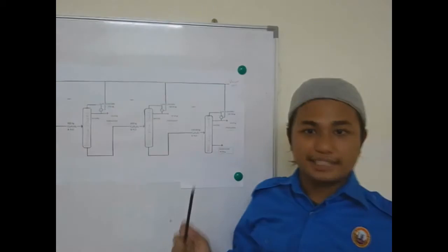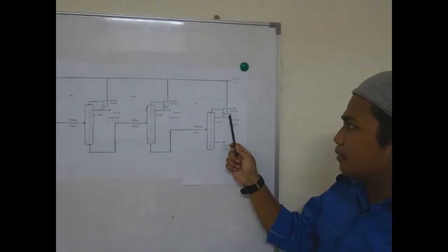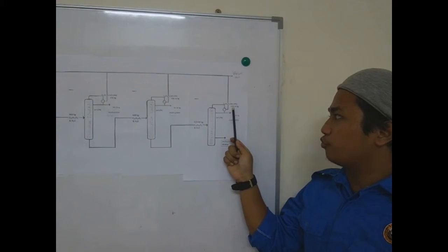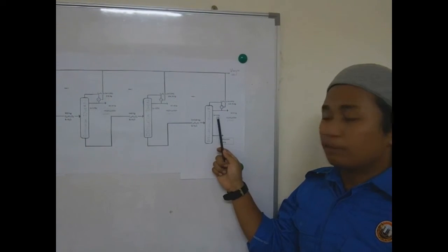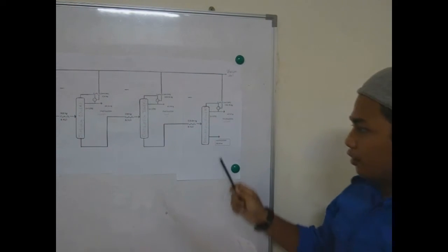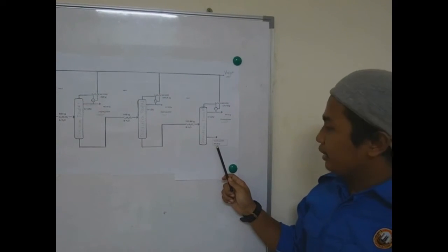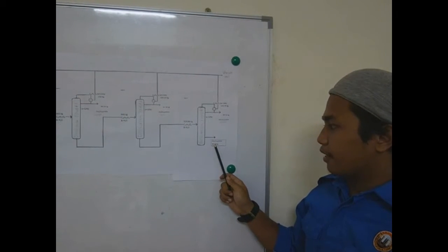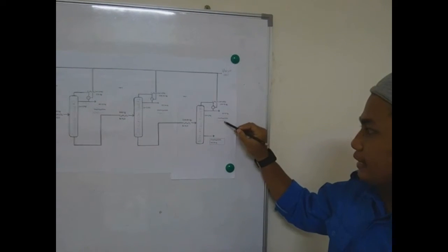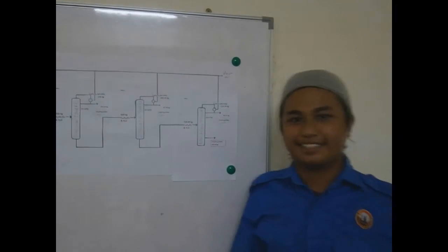Okay, the next material balance occurs in distillation tower 3, where the undistilled product that will enter the vacuum unit is 44%, which is 124.76 kg, and 12% will recycle back into distillation tower 3. Okay, for the minor product, which is glycerin, 395.08 kg, and the major product, which is palmitic acid, 347.67 kg. Okay, that's all. Thank you.